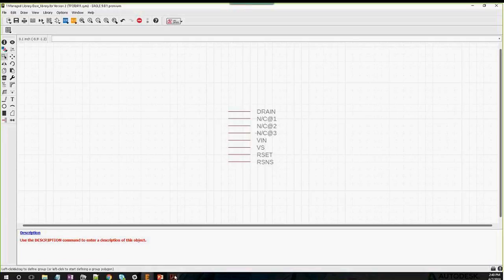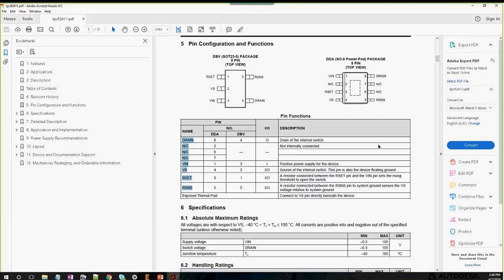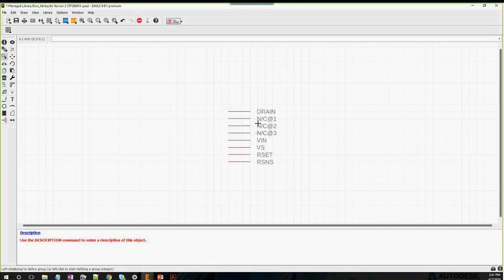We figure that most of the time users would prefer to do this than to go through the Excel way, making a complete table. But as Ed mentioned, in large BGAs, it actually may be beneficial to specify all of the IOs and what type of connections you want to make visible, all of that stuff. But usually, it's enough to just get the names. Now, you'll notice that following Eagle's convention, you can't have pins that have the same name, so they each get tacked on the @1, @2, @3, and so on and so forth.